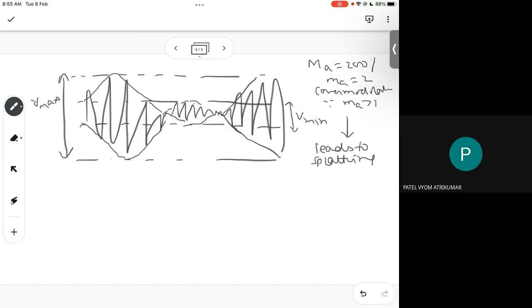And we've also seen how we measure the modulation index for such cases. You recall that for the lab purpose, we use this expression: MA is equal to (V max minus V min) over (V max plus V min). That is from the lab point of view. So you do the various cases of modulation, 100%, 200%, 0%. Those are the three typical cases, and measure the V max and V min, and you can find out the actual percentage of the modulation.